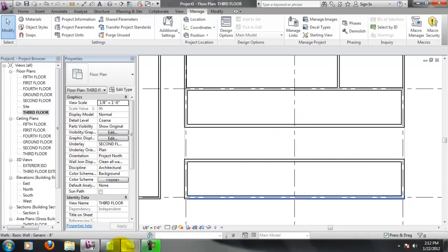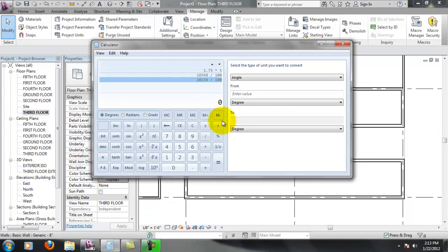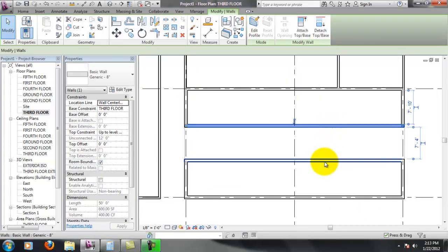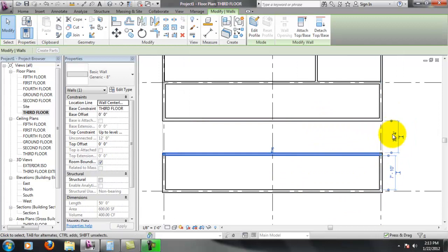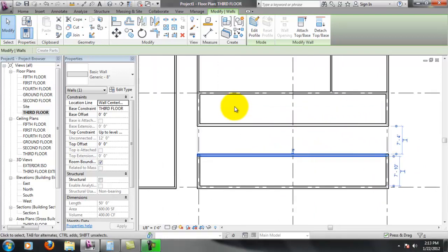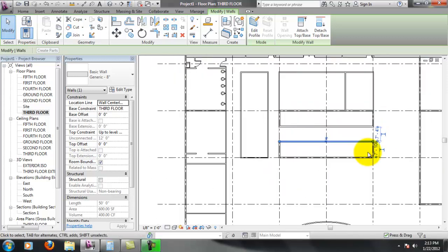So when we do that, we said the depth of the elevator is 5. That gives us 8.75. If we come here, we're actually under that considerably. So this is actually a little bit too small for 3 elevators. For even more elevators, that obviously gets larger because you need a larger space for people waiting for the elevator.